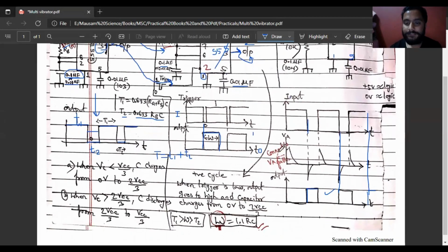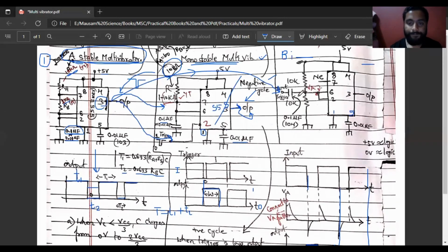Now, how can we see this charging and discharging of capacitor from this terminal? If you connect one terminal to this one, that is same input for all. Okay, one thing I want to say, why for the input in another terminal, why we change it to 100 kilo ohm? If we change it to 100 kilo ohm, then this T2 time interval will be very less, so that for a less interval of time we can give an input. So for that we convert RA into 100 kilo ohm.